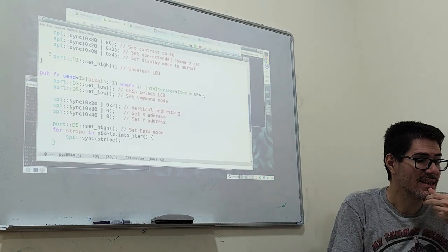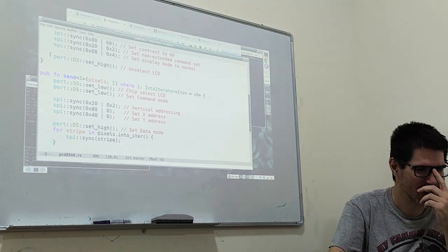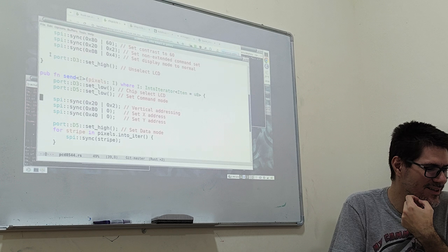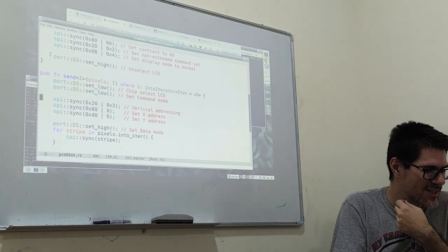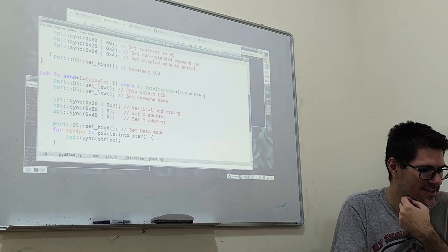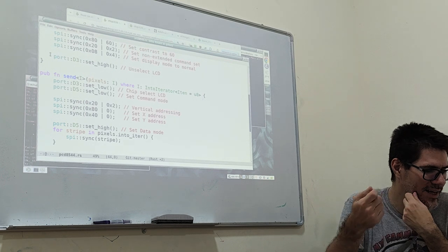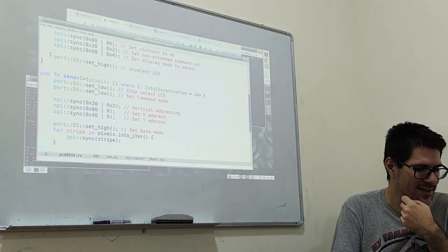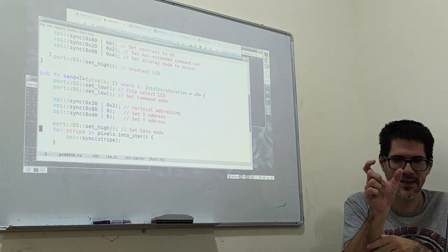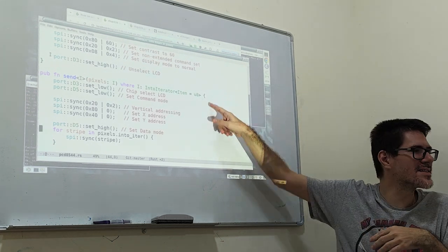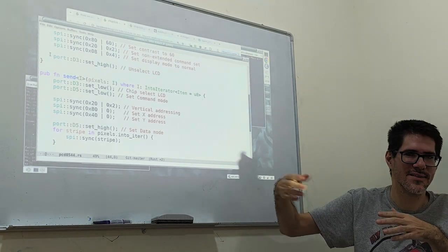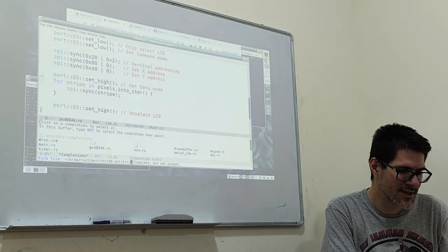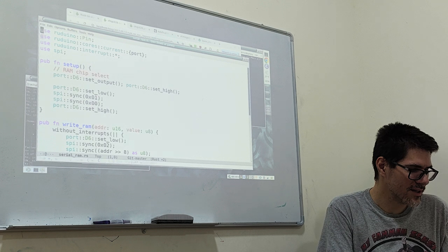Byte by byte. And then you have to look up the datasheet of the LCD to figure out how to talk to it. The datasheet will tell you that you send these magic bytes, and then you set this other input, you pull it high, and that means that instead of listening for an instruction, it will now listen for data. Then you just send out your data in 8-bit, basically 8-pixel stripes. And it's the exact same story for the memory, which, like I said, is also